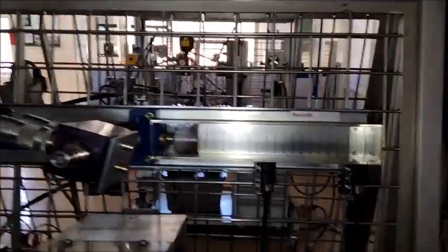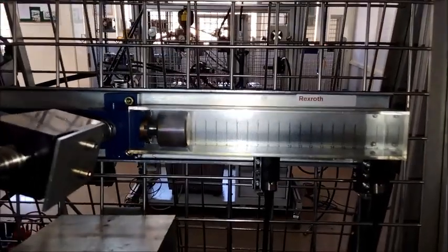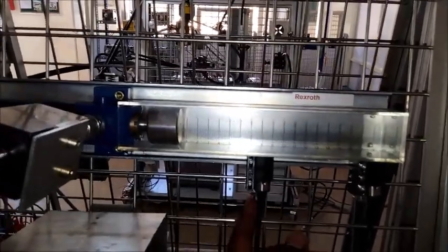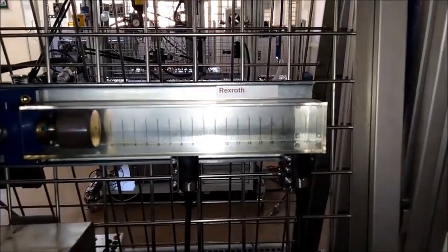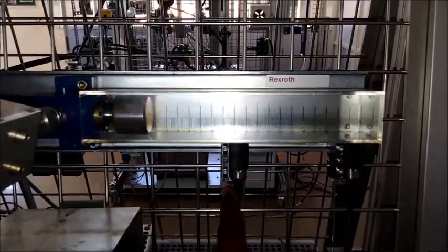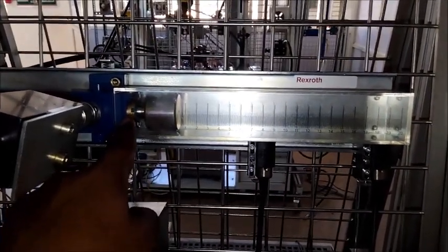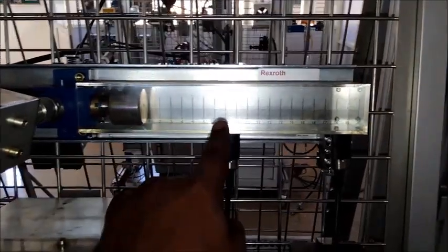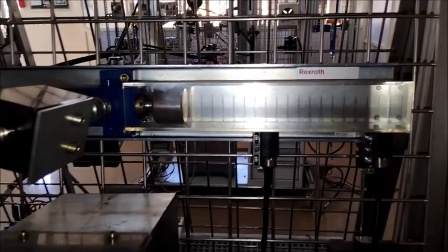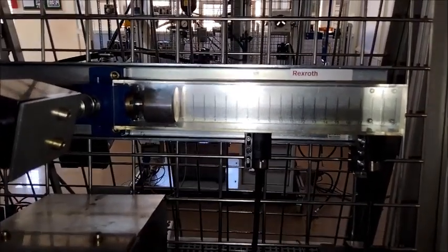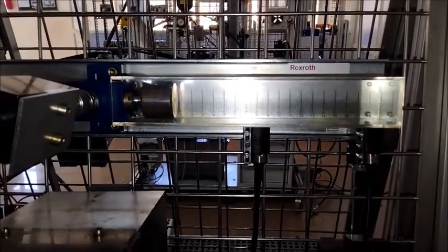The entire stroke of the cylinder is 200 mm, but we are placing sensor B1 at a certain distance, for example 100 mm, and the B2 sensor at 200 mm. Our requirement is that the cylinder rod should reach B1 at a rapid speed. From B1 to B2, we are assuming it is a drilling process, for example a metal cutting process.